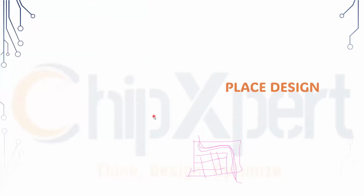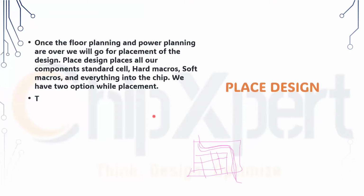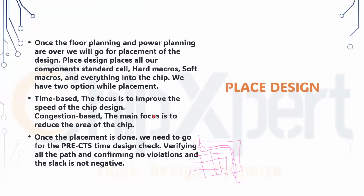Okay. Next, once the power plan is done, you are doing all the power connections in the layout. What is the next process? The next process is the placement of each and every standard cell. You have placed the RAMs, ROMs, and analog and digital converters. You have created a structure, a power plan, in a way that it will connect each of the standard cells in a pattern.